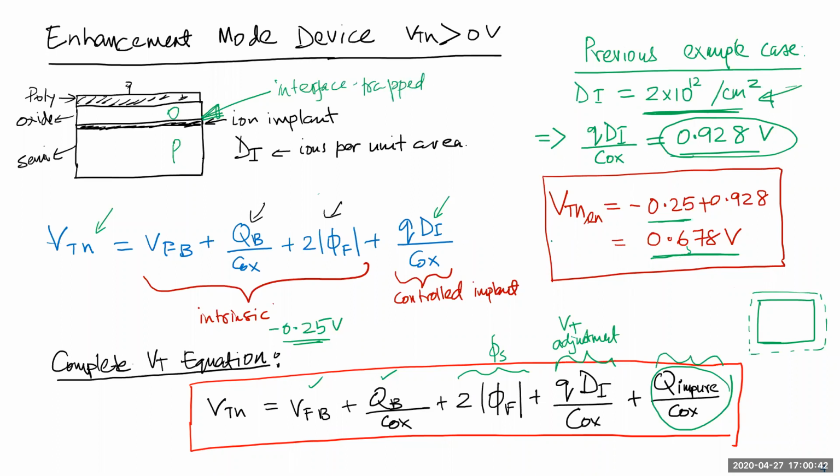It's actually a quantum mechanical phenomenon which happens. Basically, your band bends so much that you create states which will attract electrons to get trapped there. And once they get trapped there, they're just trapped with the equivalent value of negative or positive depending on the trap states. And that's actually one of the major sources of noise in analog design.